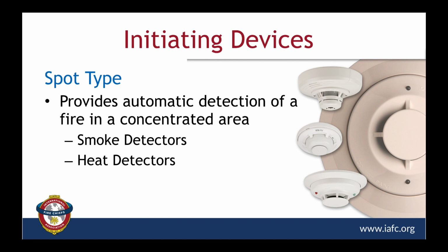As I mentioned in a previous section, a fire alarm system is activated from initiating devices that send input signals to the fire alarm control unit. Now, initiating devices are classified either as manual or automatic input devices, and those that require no human intervention are classified as automatic initiating devices, and they respond to any number of physical changes associated with a fire, such as smoke, heat, or gas.